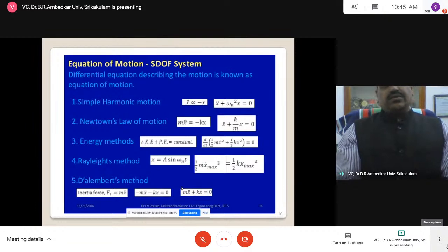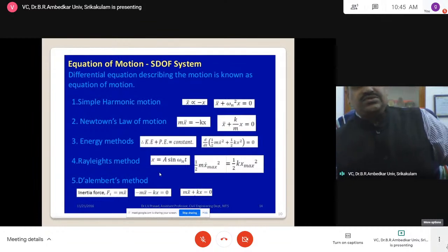So now, when you are applying a force, the spring force acting is opposite. When you are applying mass into inertia force, the spring force is acting opposite. That's why it is negative. Mass and acceleration is equal to force; the force in the direction of acceleration should be positive, otherwise negative. This is acting opposite. I will explain later with some more figures. And that is the general Newton's law.